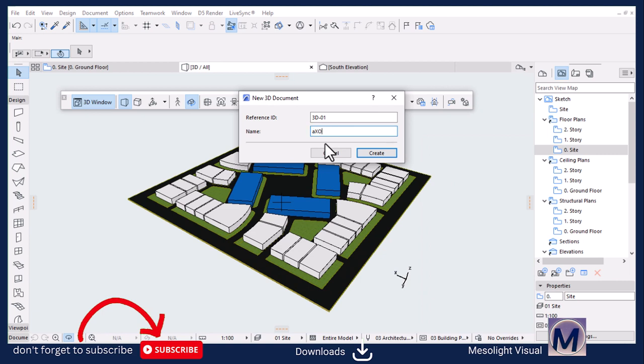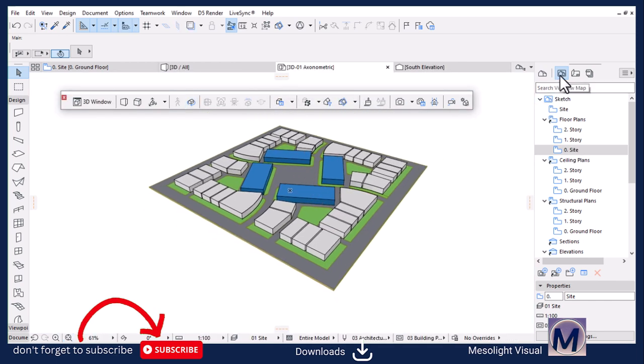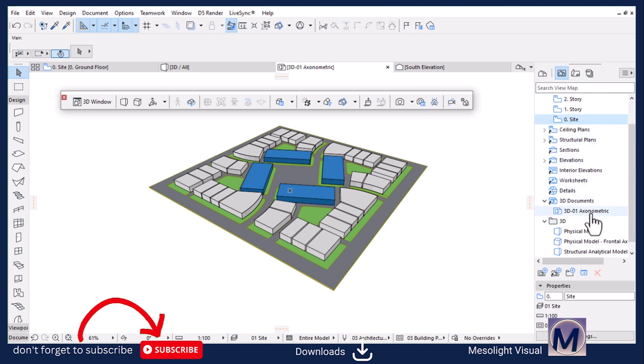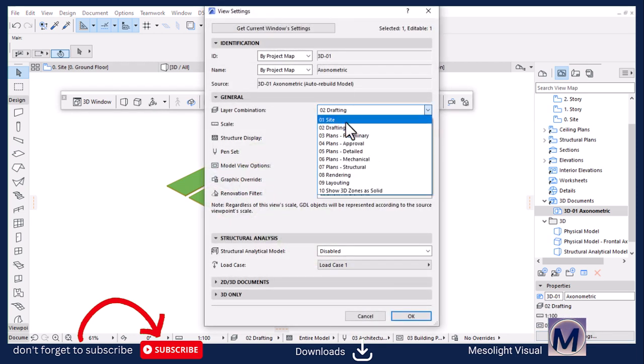I can call it axonometric. Create for the sake of this. So there we go. If you go to the view map under 3D documents, let's just collapse some of this. These are unnecessary files. 3D document, we have that saved here. You see, when I'm selecting it, some of these things disappear because it should be under a layer combination for site. So if we can check it here, this is the layer combination. It's drafting. So go to the settings. Let's set this to site.